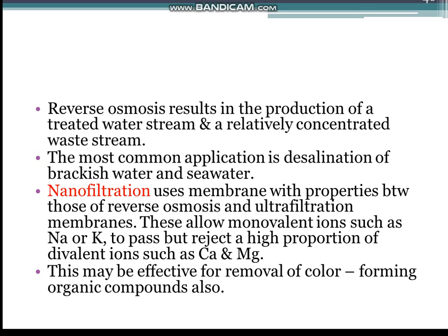Nanofiltration uses a membrane with properties between those of reverse osmosis and ultrafiltration membranes. Pore sizes are typically 0.001 to 0.01 micrometers. Nanofiltration membranes allow monovalent ions such as sodium or potassium to pass but reject a high proportion of divalent ions such as calcium and magnesium. Operating pressures are typically about 5 bar. Nanofiltration may be effective for the removal of color-forming organic compounds also.